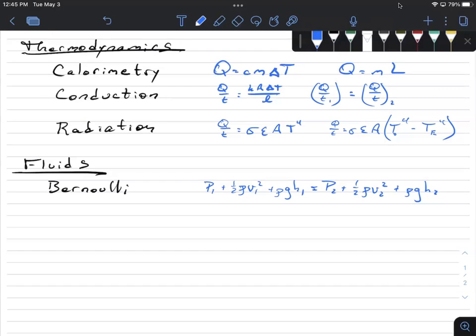If you have a gallon of water flowing through a pipe per second, and then you constrict it, you still need a gallon of water flowing per second out of the other side. So in order for that to be true, since you now have less room for the water to flow, the water has to speed up. So the speed of the water changes because you've changed the size of the pipe.